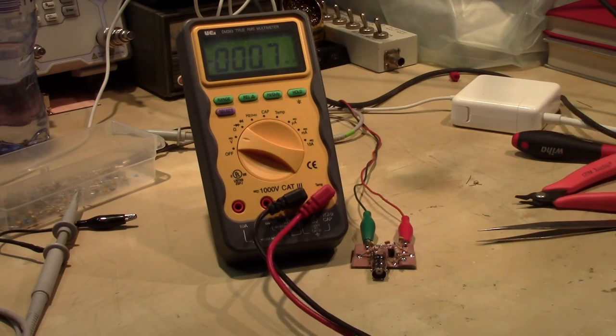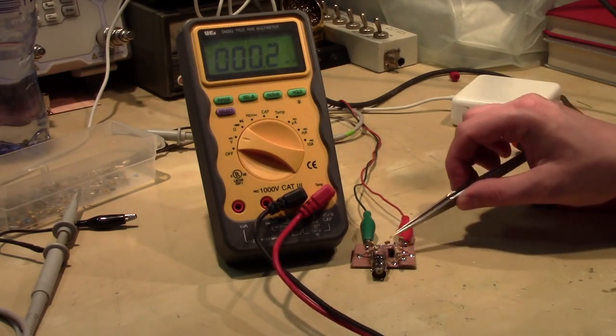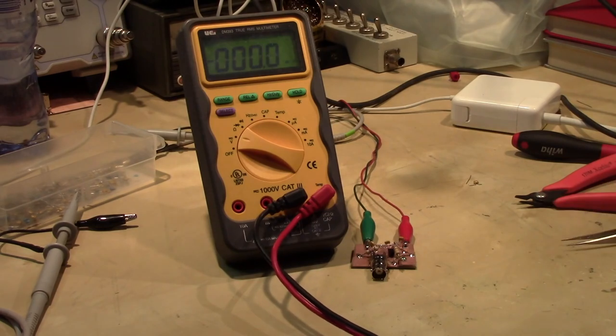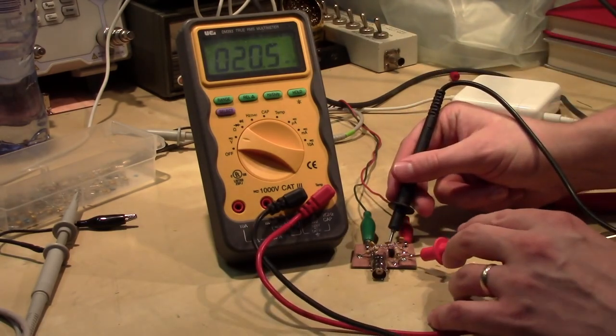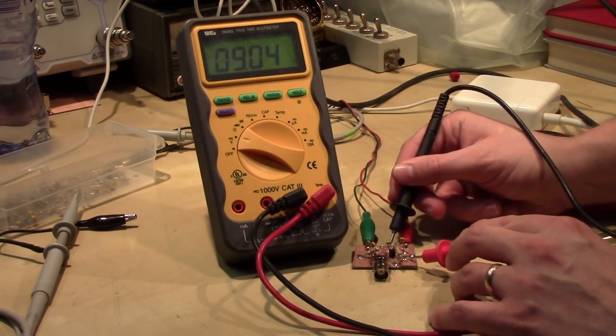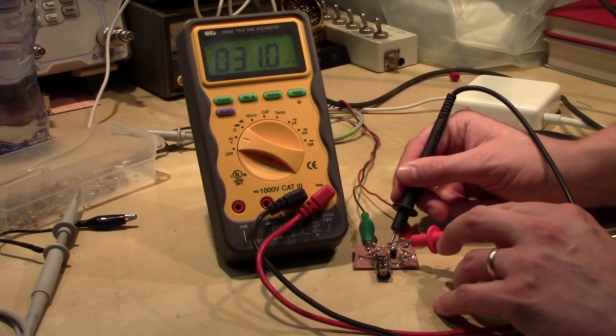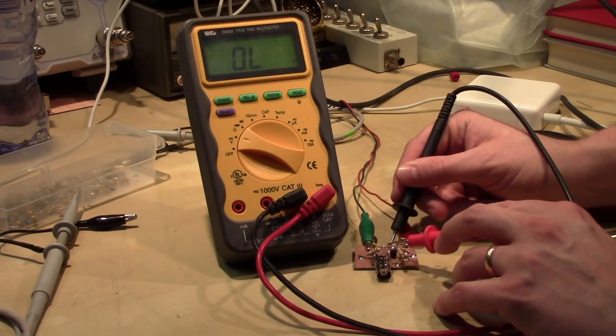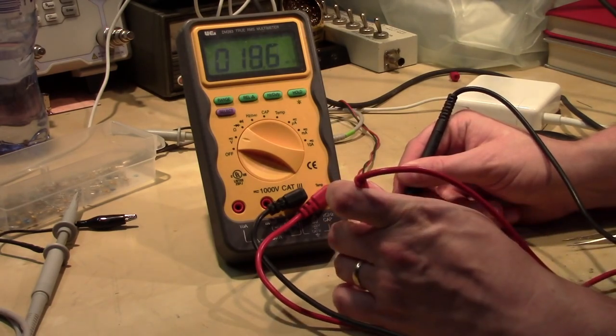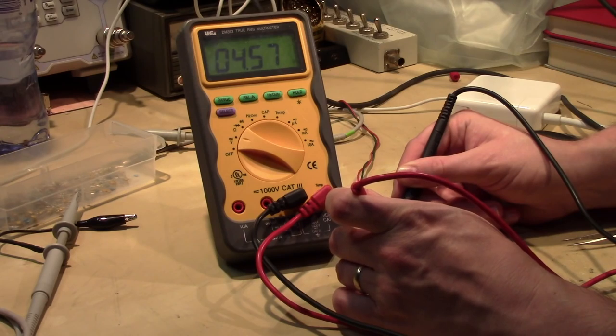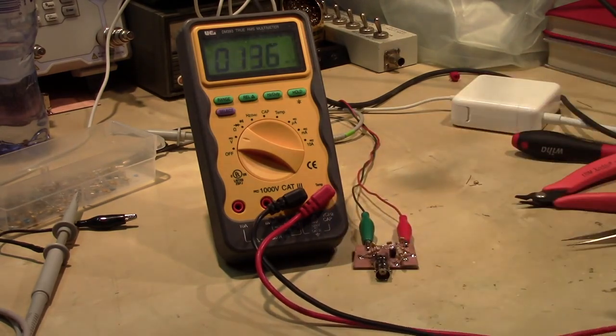So I have all the DC biasing set up here with the resistors and the transistor. Before I actually add the crystal to get the thing to oscillate, I want to check my DC parameters. I should have 9 volts on the power rail. The base voltage should be about 5.2 volts. If I can get on there. Yeah, 5.18, that's pretty close. And the emitter should be about 4.5, 4.6 volts here. 4.57. So that all looks good. Everything seems to be biased properly. So I'll add the crystal in and we'll see if we can get it to work.